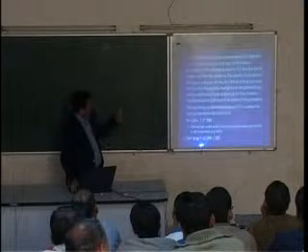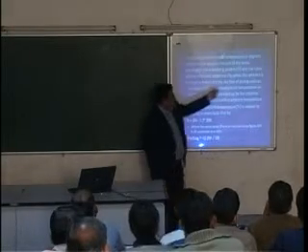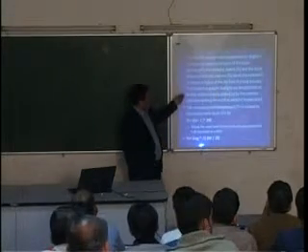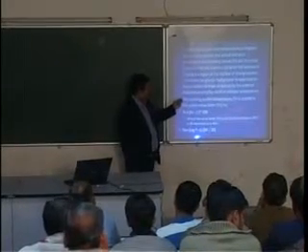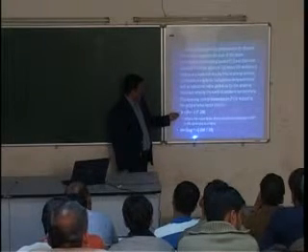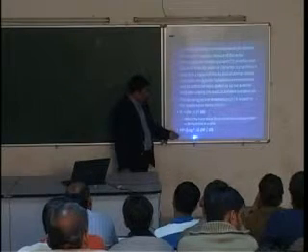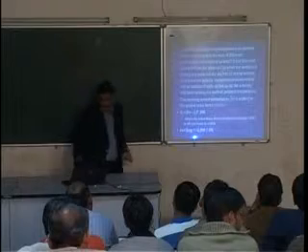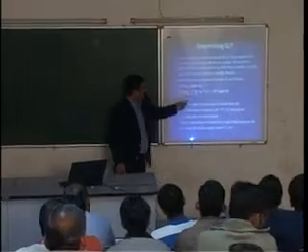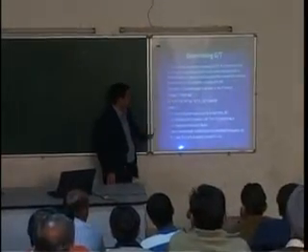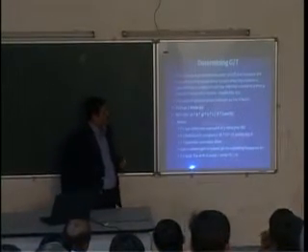And this is one of the methods I told you about: you point the antenna to a sky region free of strong sources, with only background galactic sources, and there will be noise picked up by the side lobes. Then you take the receiving system's noise temperature, you get the T, and then you convert this T into noise figure Fn. Then one can easily measure the sun and cold sky condition, see the measurement of the Y factor, and find out the G by T using this expression.